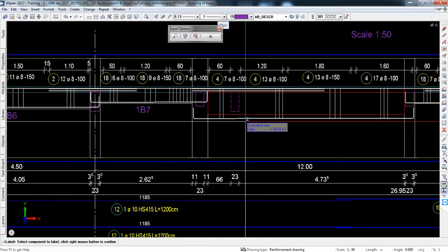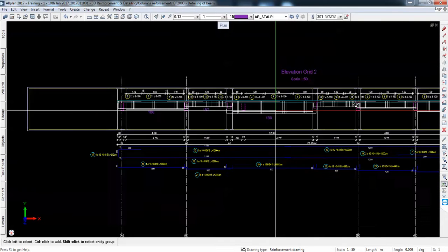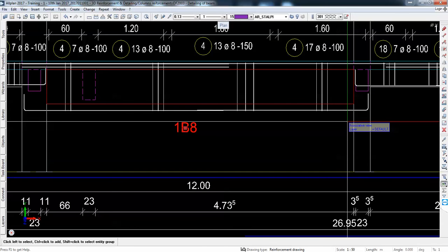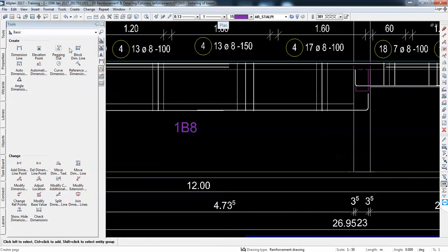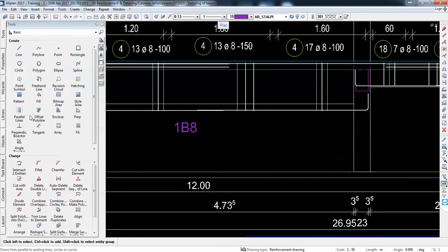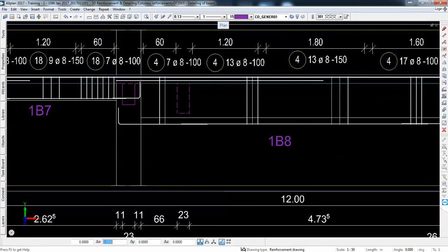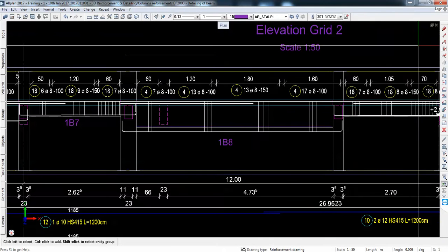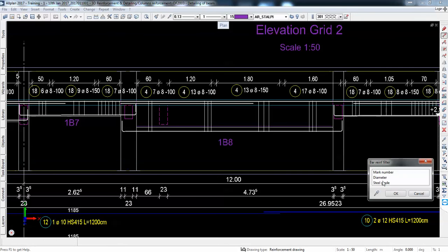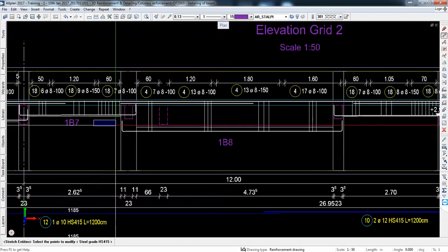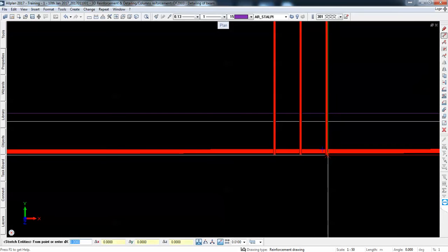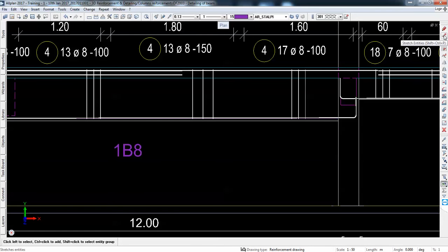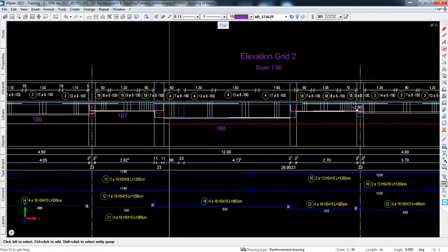So basically once I need to do this, there's also a mistake I identified. We see here that the beam is here, so I need to do this correction now. It's no problem if I'm doing it in the detailing stage, as it will update the drawing, the 3D model and everything. So now I can do both changes, moving the longitudinal reinforcement and the stirrup using just this filter for steel grade. Okay, pick up this one and change it here. So this stretch entities also acts like a move function. So I move them and corrected everything.